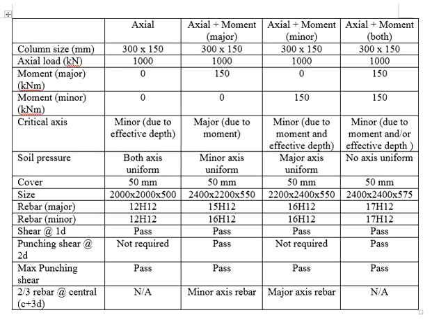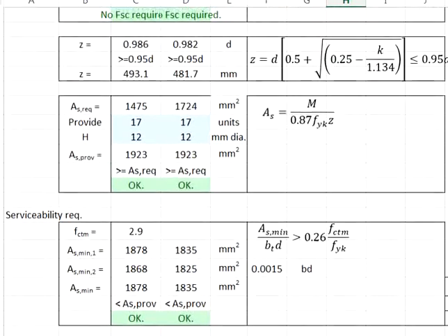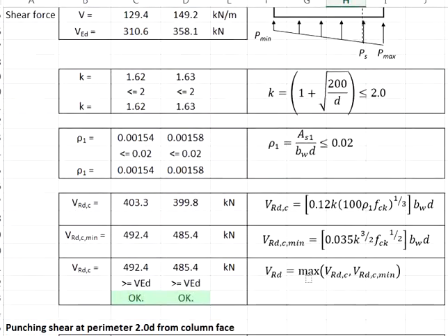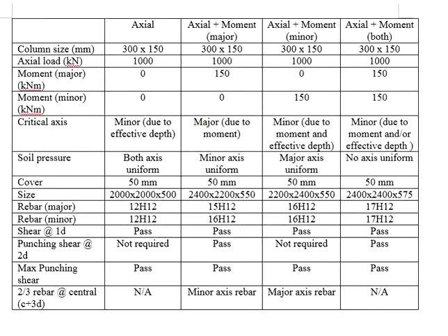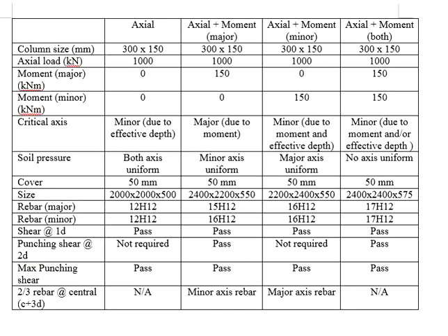The main reason is the effective depth. Smaller effective depth will require more reinforcement bar to take the moment, and also will give you a less effective shear region to take the shear load. Personally, I would recommend that if your pad footing design will have moment in both axes, regardless of the magnitude of the moment, you better check both axes. Sometimes it is harder to tell which side will be more critical until you've done the calculations.